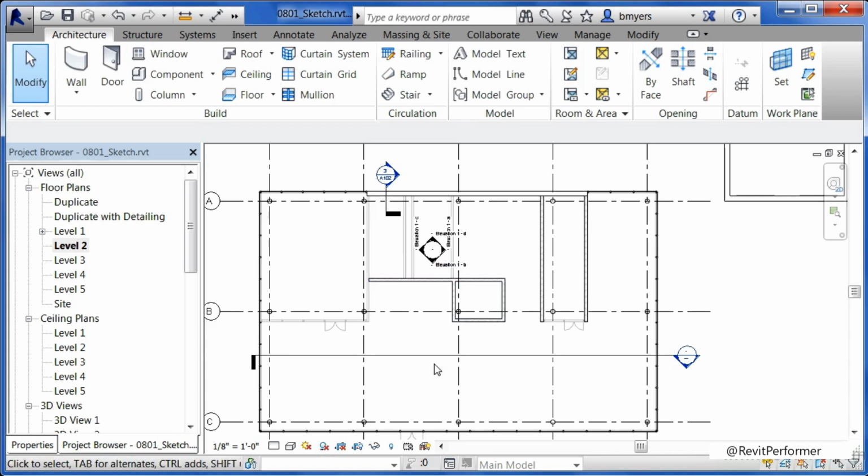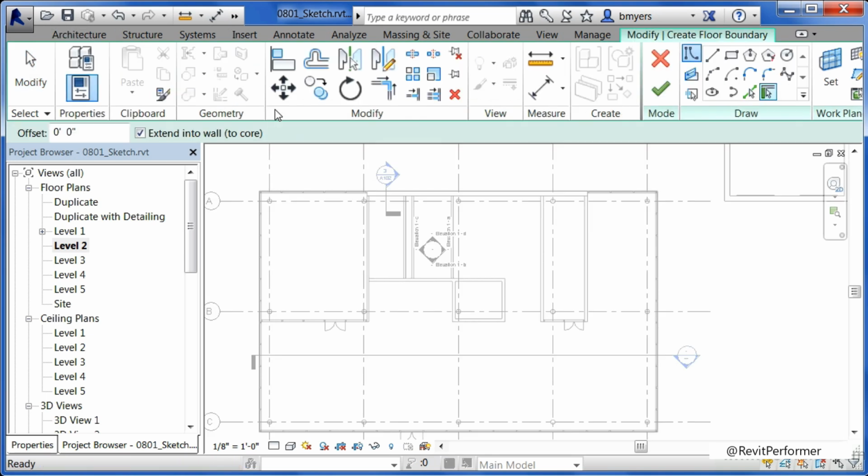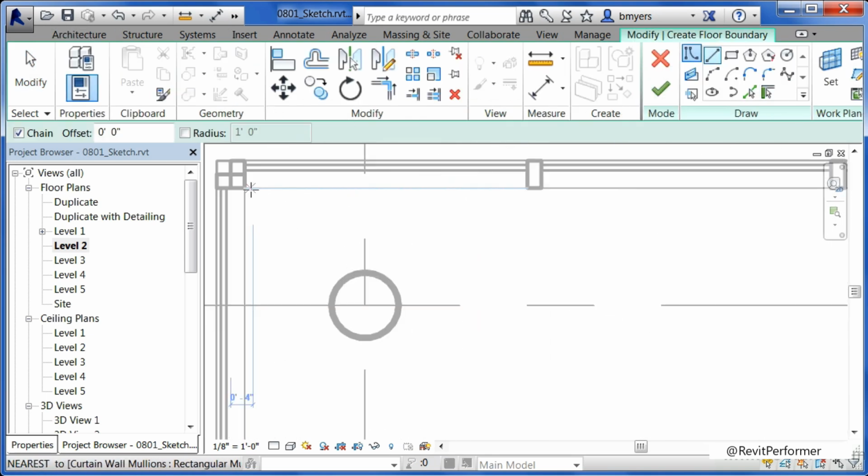These ones that are darker, they're coming up through the second floor and going up to some of the floors up above. Now, we can always modify our floor so that it will have holes for each of these walls, or we can adjust the walls themselves so they'll just go up to the underneath side of the floor. We have a variety of different things that we could do. But in this case, move up here to the Architecture tab again, select the Floor tool, use the Line tool this time, and let's start to draw, beginning with this intersection right here.